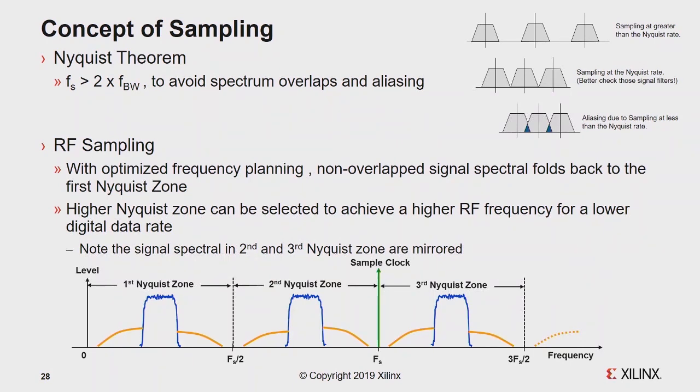So here is the signal of the DAC, the bottom right diagram. The DAC is processing the digital signal to analog. If you carefully do the sampling with enough bandwidth, you don't have aliasing. So we will have a copy of the signal in each Nyquist zone. If you're doing undersampling, like when your signal is maybe 5 gigahertz but you sample at only 2 gigahertz, we can use the higher Nyquist zone, and then you can save some sampling clock power and data converter capability.